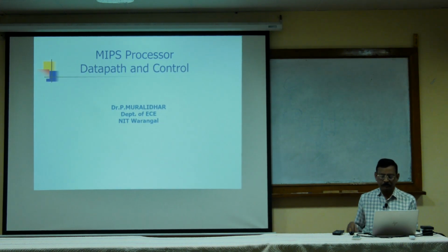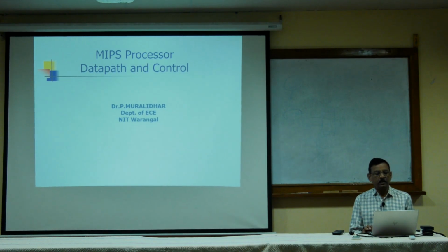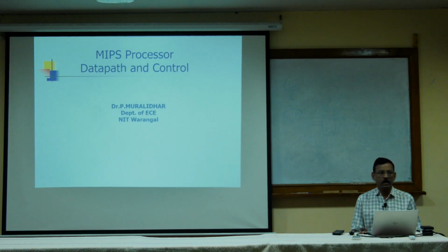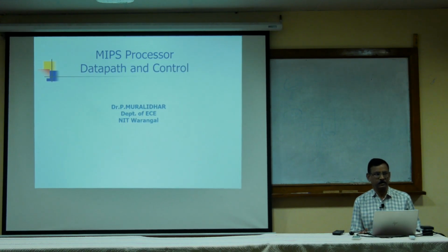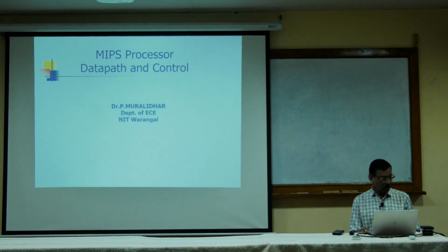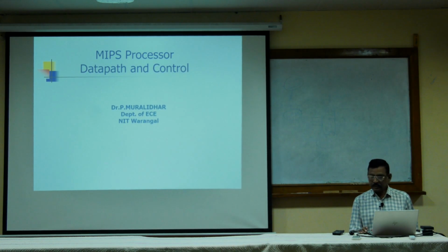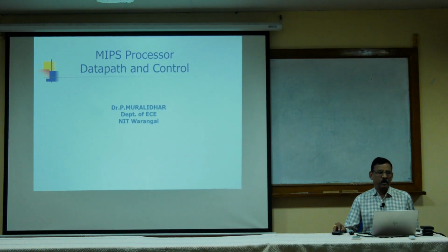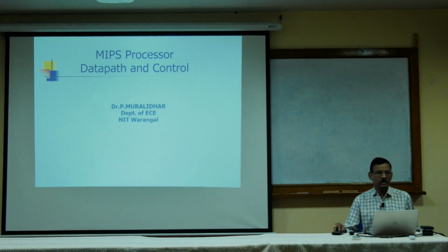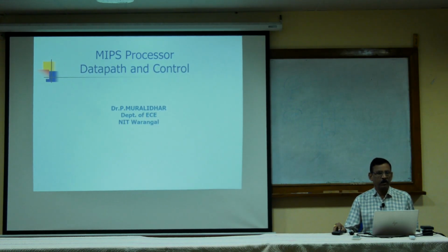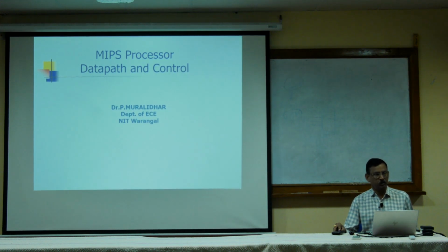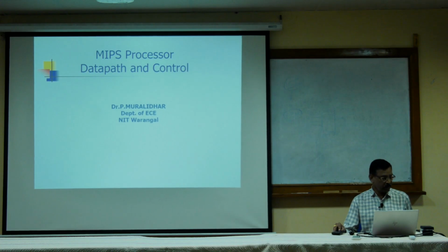In this processor, the MIPS processor, MIPS stands for microprocessor without interlocked pipeline stages. It is a 32-bit RISC processor with the complete RISC architecture, but I am not going to design the total as it is. This is a customized one. We can develop our own small instruction set with a small controller.